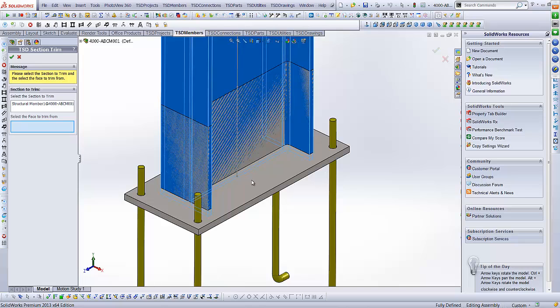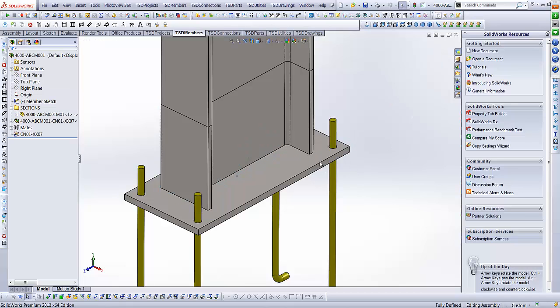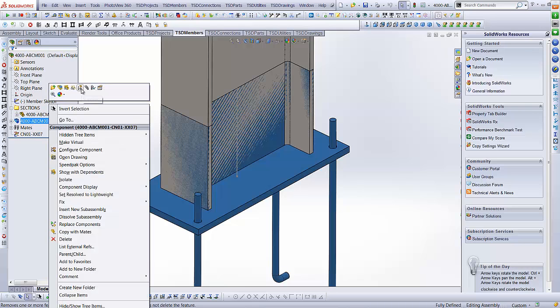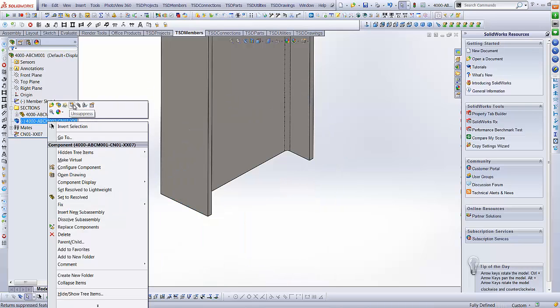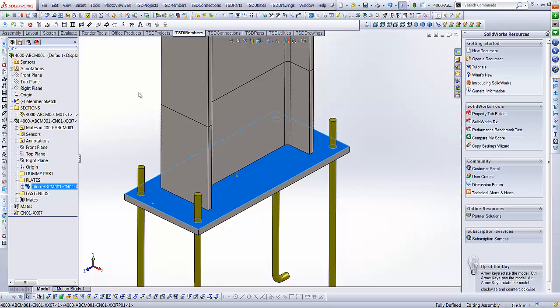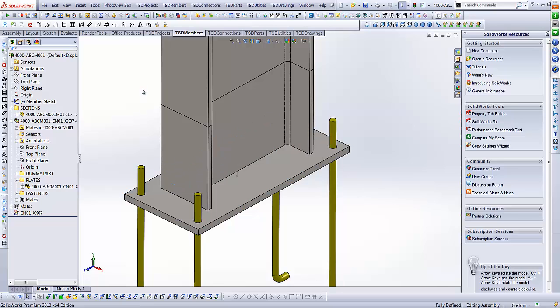I can select the main weldment and then select the face to which it's going to attach. Now if you can't select the face, it's just SolidWorks telling me that we haven't updated the connection in SolidWorks itself. You'll notice that I cannot select anything. If you just do a Control Q and a save, then suppress it and unsuppress it, and this is a bit weird, you then can select it. Okay, just letting you know.